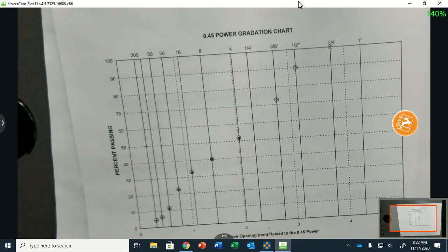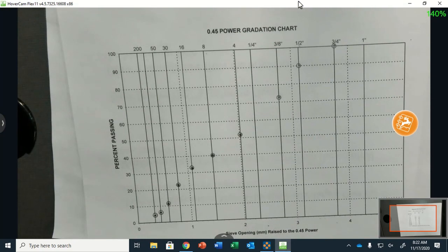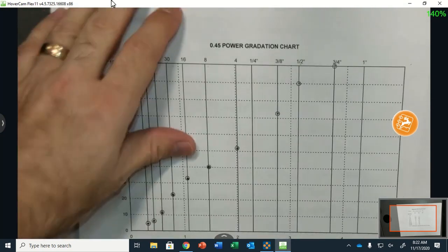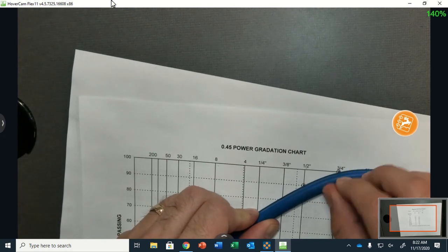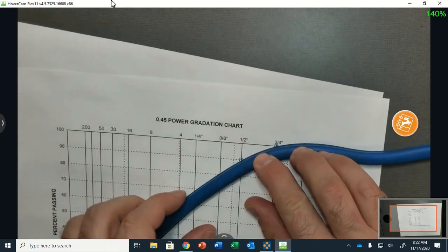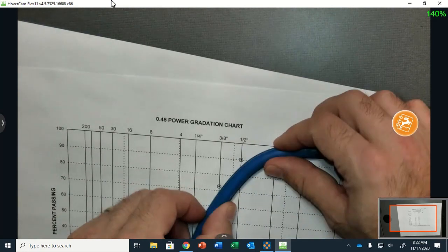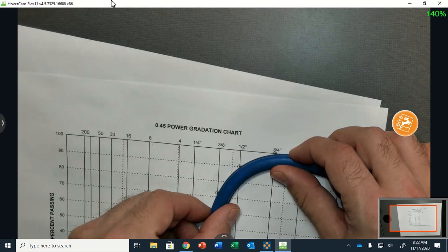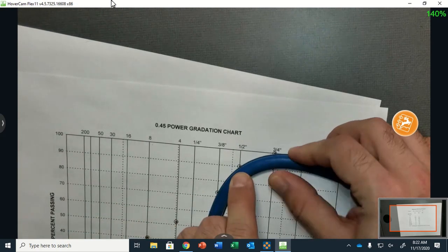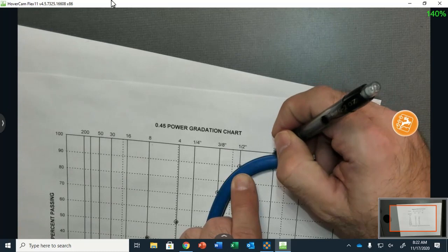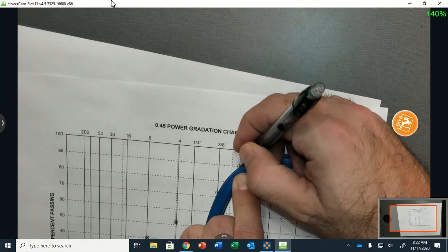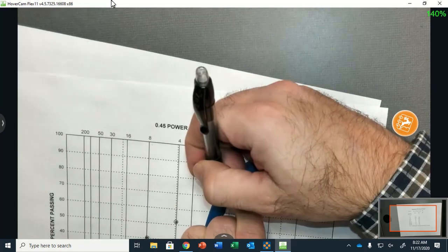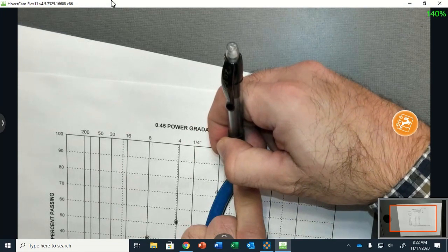So now, flexible curve, remember this guy? Remember, we connect 3, it's a smooth transition. So you just put this sucker on here. I do not draw through my circles. I connect my dots. Gotta get this bent. Okay, so you can see I have my line. Here's my dot, dot, dot. I have this connected. I start here, do not go completely through the circle. I stop at the edge of my circle.